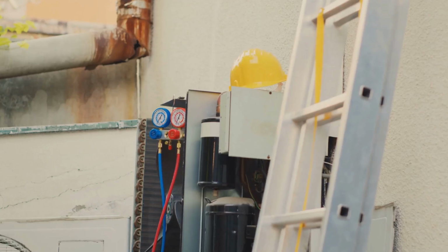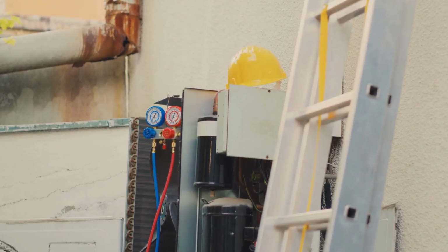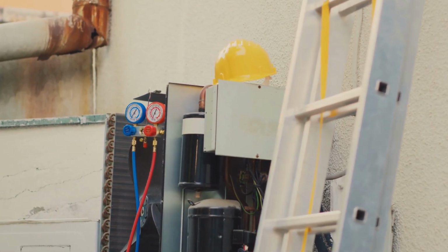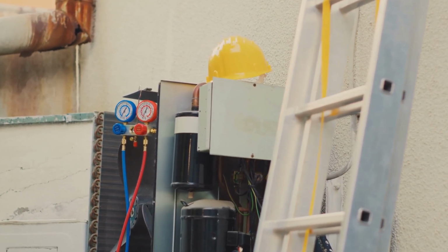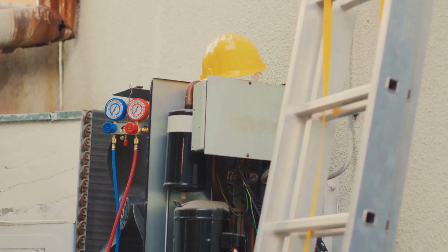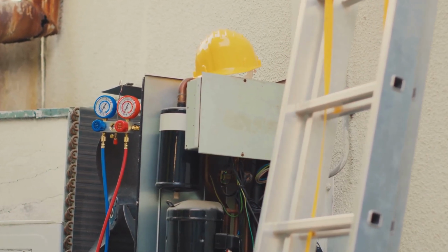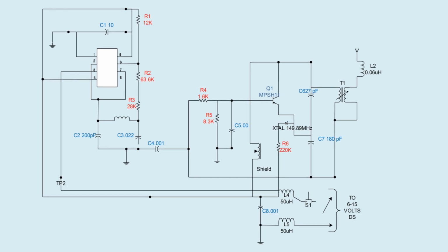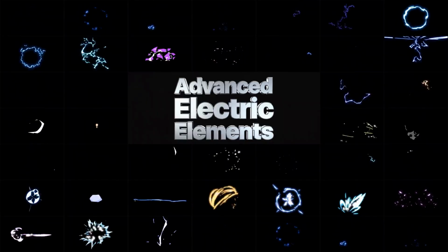Section 4. How these parts work together. These components work as a system. The thermostat calls for heat. The sequencer activates the heating stages. The elements begin to produce heat. The high-limit switch monitors temperature, and the blower distributes the heat through the home.